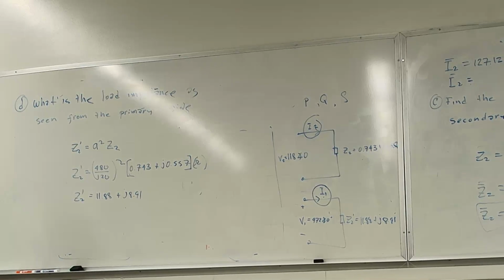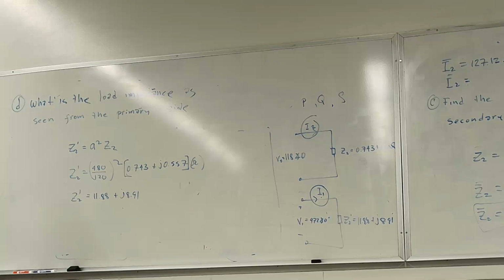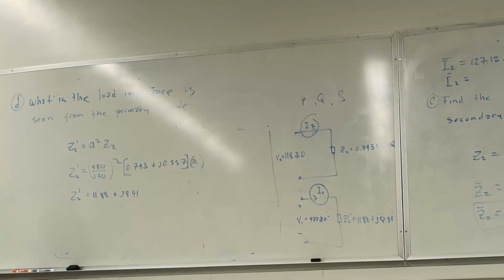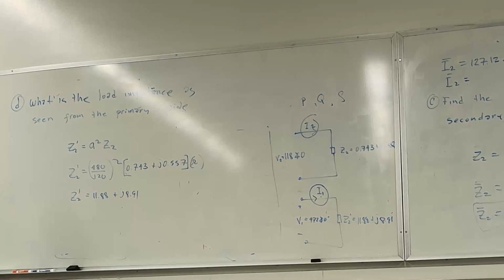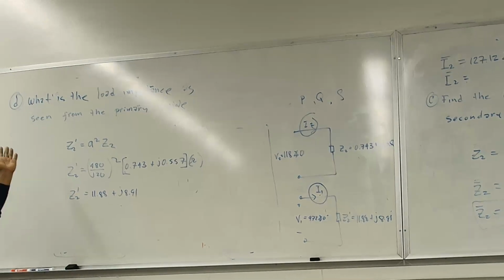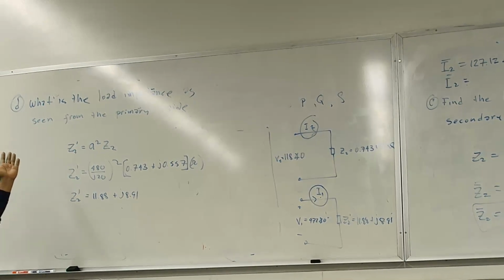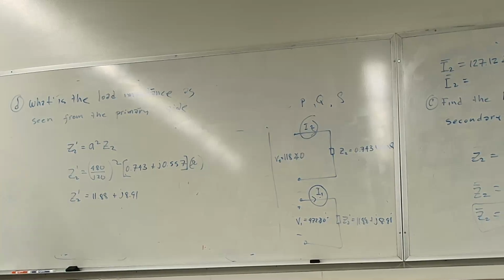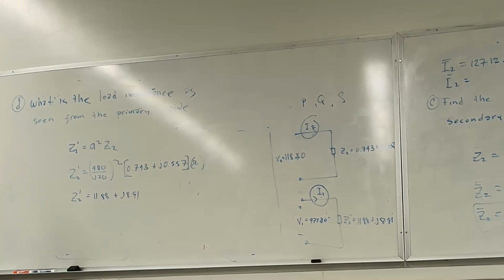Okay, so with that, remember we talked about what that turns into is the conductors that you're using, right? So for the same rating, the conductors on the secondary are going to be a little thicker than the ones on the primary. But the spacing in between the terminals on the high side is larger, you need more spacing on the high side than you need on the low side. Make sense? Okay. All right.